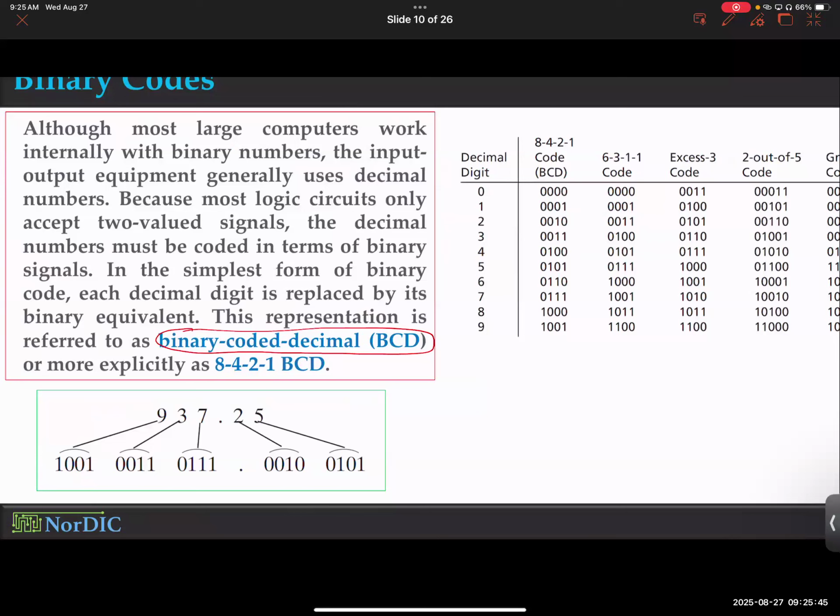It makes it easier for us to map it into hardware. If you think about a 7-segment display, how many of you have seen a 7-segment display? Okay. You see that in a calculator, for example, right? It doesn't have very high resolution, but it has 7 segments, and you can use those 7 segments to show any numbers, any digits, even some letters of the alphabet as well. So it's easier to control those 7 bits using BCD coding sometimes. We'll see that at some point.